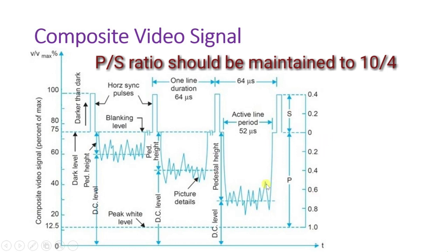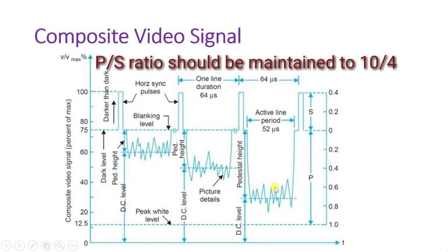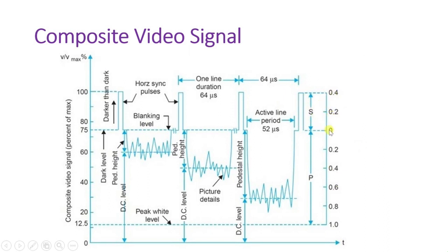So the horizontal blanking time is 0.16 times 63.5 microseconds equals 10.2 microseconds, approximately. Now, we subtract this value from the time H, which is 63.5 microseconds. 63.5 microseconds minus 10.2 microseconds equals 53.3 microseconds, so 53.3 microseconds is the time required for visible viewing, without blanking, in each horizontal line. To blank H, a horizontal retrace is required.